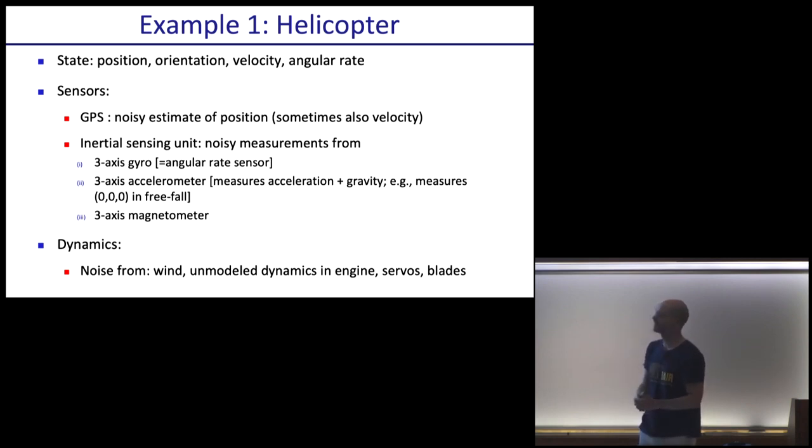Some tricky things: if you have something that generates its own magnetic field, like some magnets on your system, or high currents that induce magnetic fields, then you might perturb those measurements and not really get the Earth's magnetic field, but something else. Or if you fly near a power line, it might perturb the measurements you're getting.